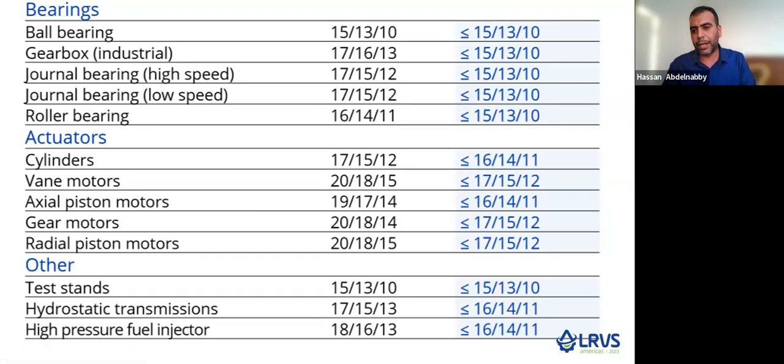If you increase the cleanliness level of your oil, you will increase the lifetime of your oil maybe by 10 or 11 times, depending on the level of cleanliness you have reached. And of course, this can reduce the amount of secondary damage from these contaminants that can lead to more problems.